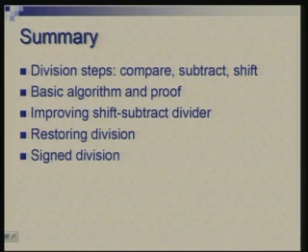Then with slight changes, we were able to modify this algorithm for signed numbers, and remember that when you are talking of signed division, we are doing addition and subtraction with 2's complement numbers. Therefore, addition and subtractions are not conscious of whether the numbers are signed or unsigned, as long as the representation is 2's complement. So, that fits in nicely, and we can have the algorithm work on 2 signed integers and perform division. Okay, I will stop at that.